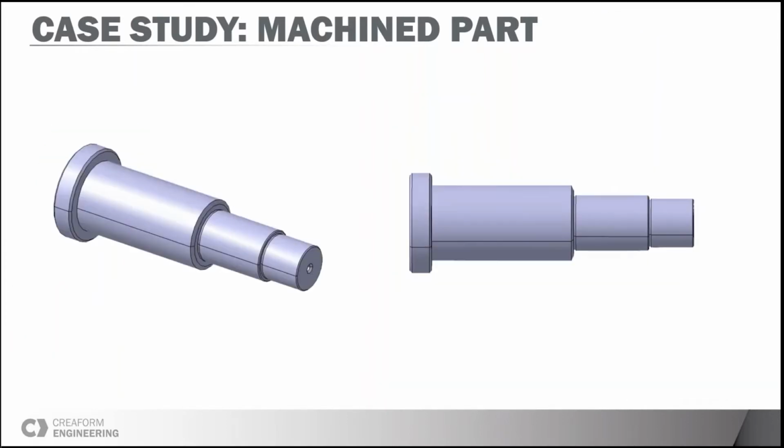So how does it translate in terms of datum on a drawing? First, we add the diameter that can constitute our datum A. Then we have the shoulder of the spindle that can constitute our datum B. A good thing to remember when defining datum like this is that it will often be a good idea to ensure that the datums have a good relation between themselves. In the example here, we could define a perpendicularity control on our datum B like this, and that will ensure that it will always keep a good orientation in relation to datum A.